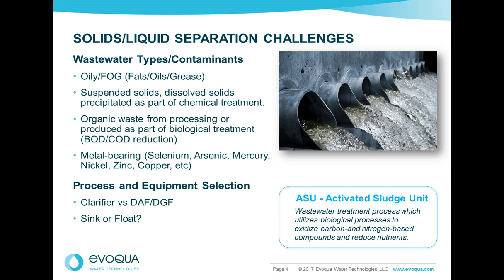organic solids, either entrained in the process water streams or produced as part of biological treatment, such as an activated sludge unit. These can present real challenges because of the variability of the composition or the low density of the solids formed in these systems. The wastewater treatment often must achieve removal of metals to meet effluent limits, metals which are often insoluble or incorporated into an insoluble matrix.